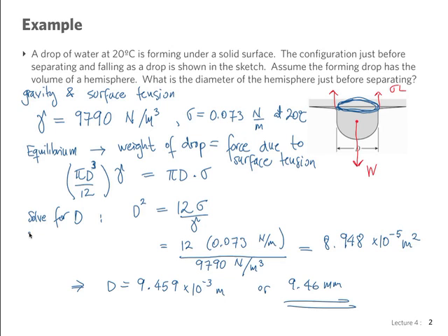So is it always going to be the case that right before separating, for a fluid attached to the surface at the bottom, it's going to be like this? It's a simplification that we're making here, but it makes sense because in reality, as we saw in some of the movies last class, the contact lines travel, and perhaps the drop will slowly detach and the circumference will be smaller. But if the circumference is made smaller, the surface tension force is going to be smaller and smaller, so it'll detach even quicker.